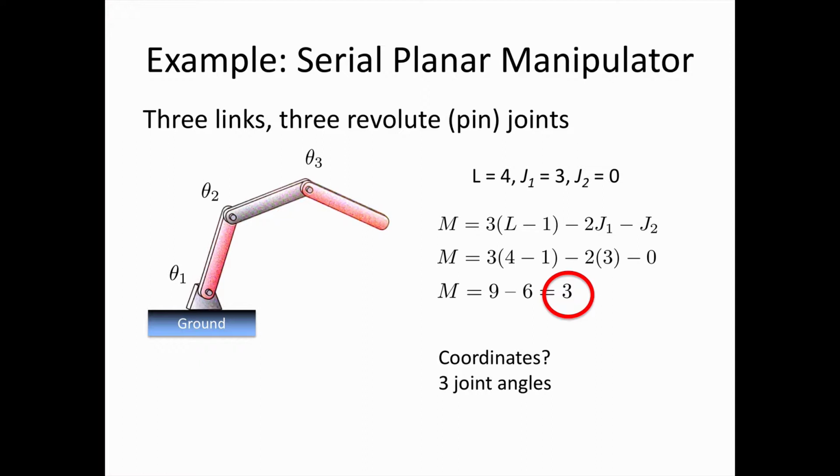In the last video, we talked about robotic systems and kinematics and introduced some of this terminology, where these generalized coordinates that describe the position of a mechanism, in robotics terminology, define the configuration space. So the values of theta 1, theta 2, and theta 3 combined are a point in the configuration space.